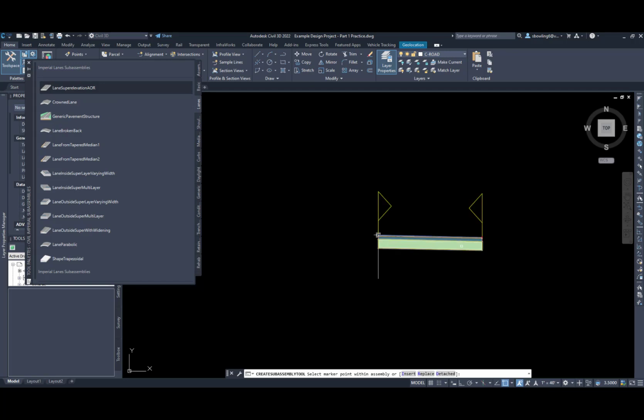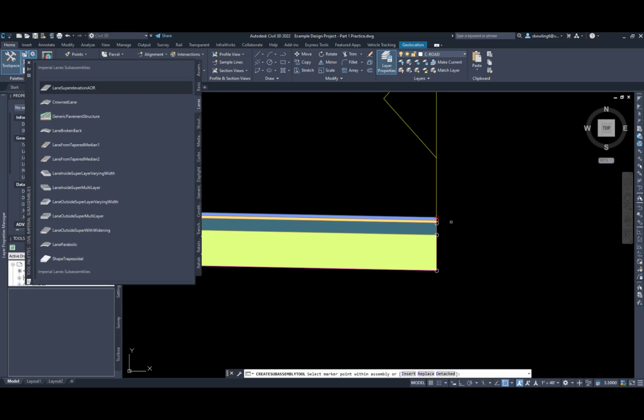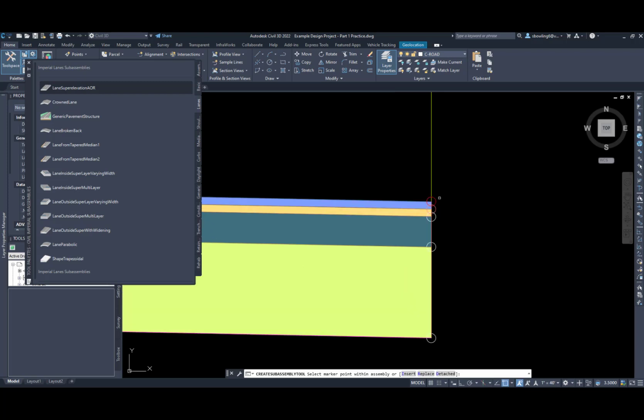I'm going to go ahead and draw out the assembly, and then I'm going to make sure of the dimensions. Now, be aware that there are little circles. These circles are tie-in elevations. So if I wanted to do a cut fill analysis or a quantity takeoff analysis, these help us code what is asphalt, what's base, what's subgrade. I'm not going to worry about that this semester. Let's just talk about the general.